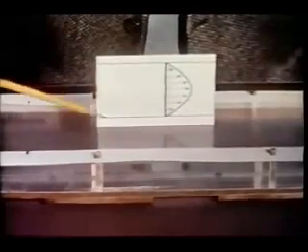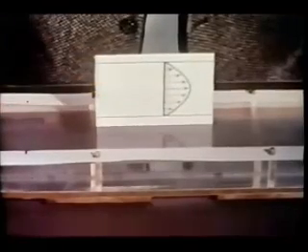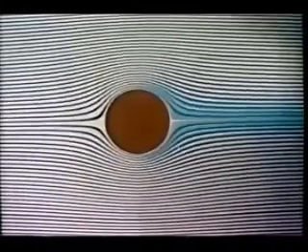In the Hele-Shaw apparatus, colored fluid is injected into the stream through a number of regularly spaced holes, and since the streamlines originating in any neighborhood remain close to one another, the lines of color remain sharp. When they are deflected by a thin disc placed between the sheets, they assume the same form as those of an ideal fluid when deflected by a cylinder of the same cross-section.